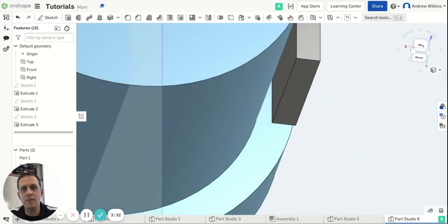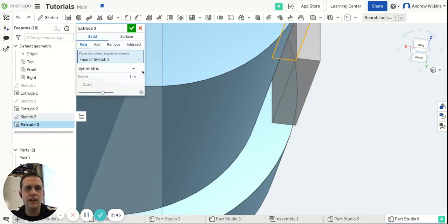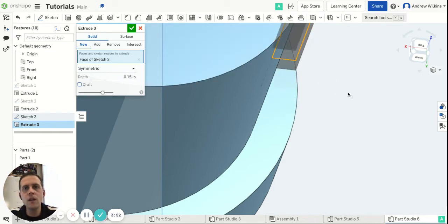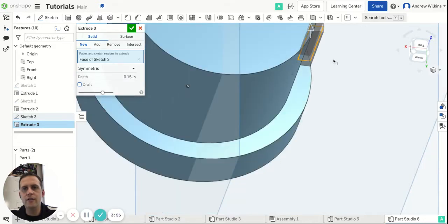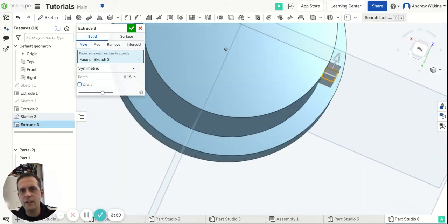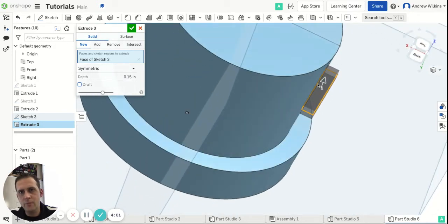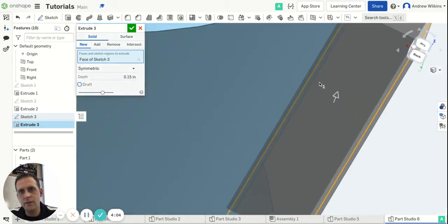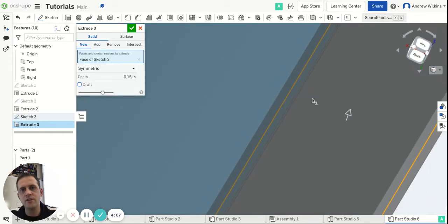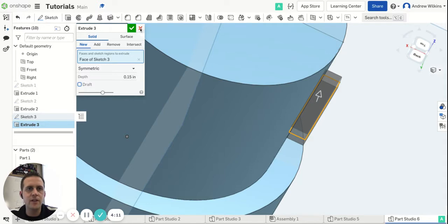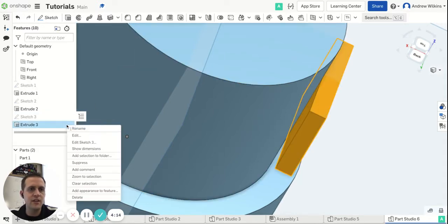And if I don't want that gap, then the way I just did that is not going to help. Now, I could maybe come in here and extrude that surface to the face of this, and that would be enough. But if I make this extrusion smaller, like it would have been in my original design, like 0.15 inches, I don't have a lot of room to get back in between my cylinder and my new sketch in order to connect those surfaces. So it's going to be a lot easier if I create a separate sketch and then extrude that one instead.